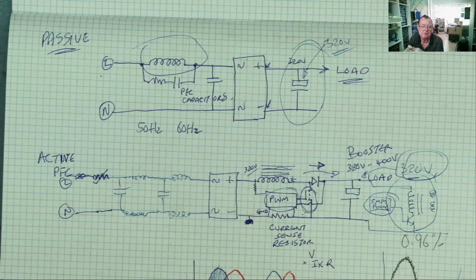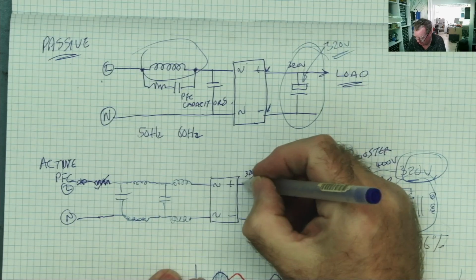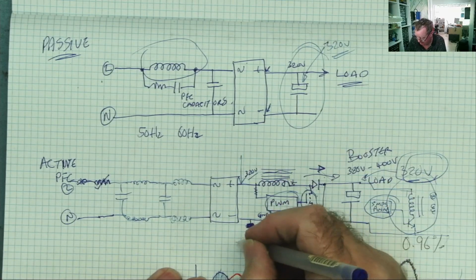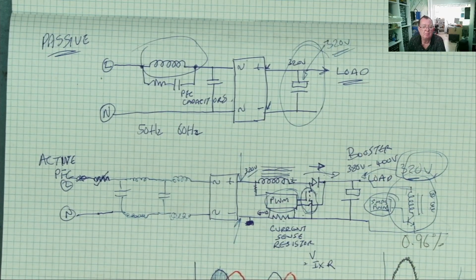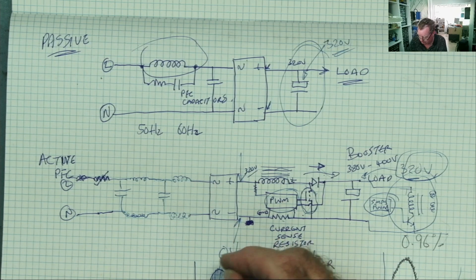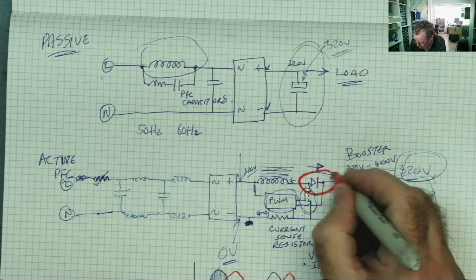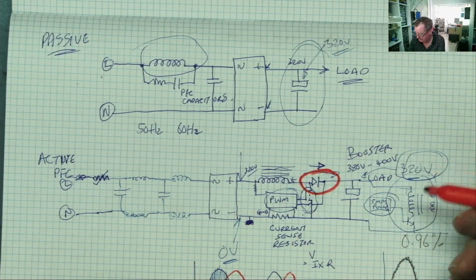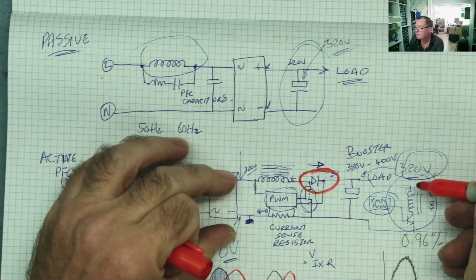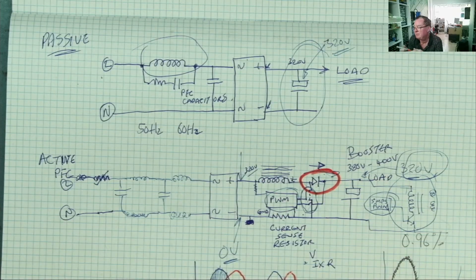Same situation. So, clever, I'll test across the bridge rectifier, because I can't get to that. I measure across here. I will always read 0 volts. Why? Because this diode, this one, is preventing you from reading the voltage across the capacitor by reading across the bridge.